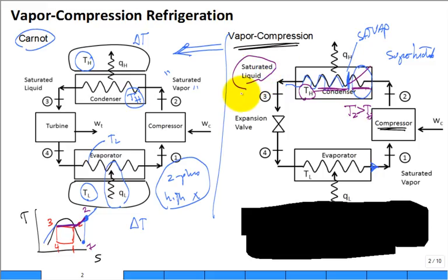That's saturated liquid. Then we put it through not a turbine, but we put it through an expansion valve, which has some irreversibility. So it has some higher entropy: S4 coming out is going to be greater than S3 going in. The second law analysis. So when we come over for 3, we dash line over to state 4, and 4 has a higher S than 3, than it used to have.